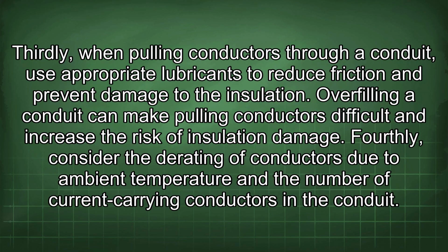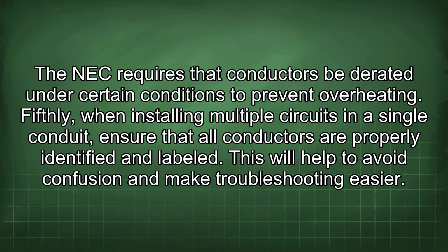Thirdly, when pulling conductors through a conduit, use appropriate lubricants to reduce friction and prevent damage to the insulation. Overfilling a conduit can make pulling conductors difficult and increase the risk of insulation damage. Fourthly, consider the derating of conductors due to ambient temperature and the number of current-carrying conductors in the conduit. The NEC requires that conductors be derated under certain conditions to prevent overheating.